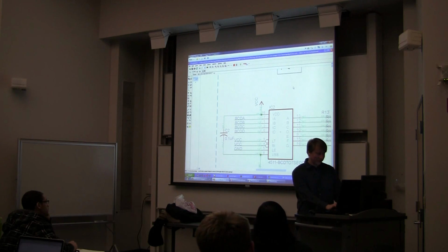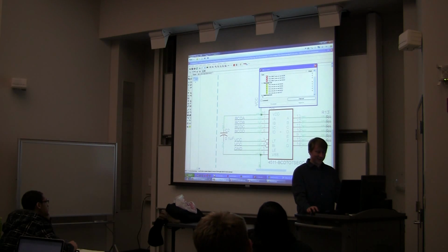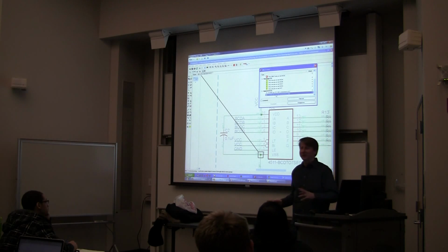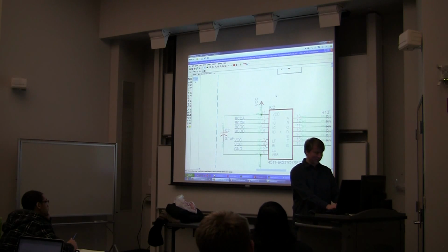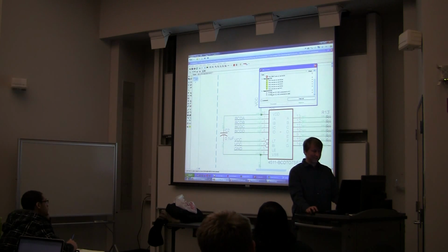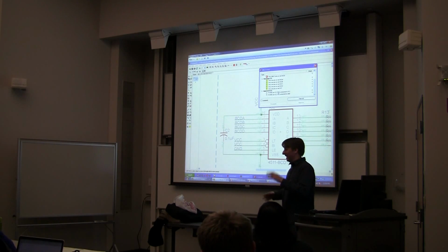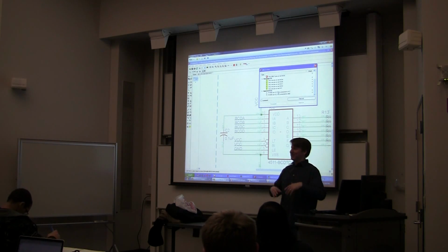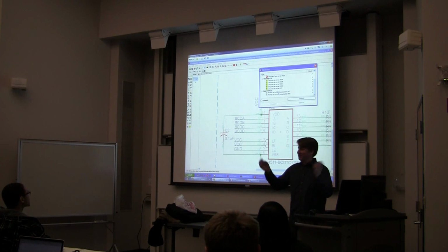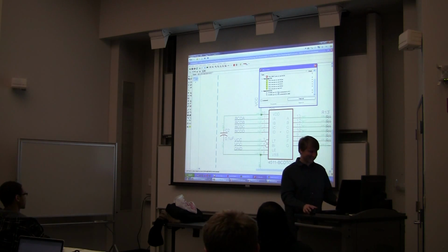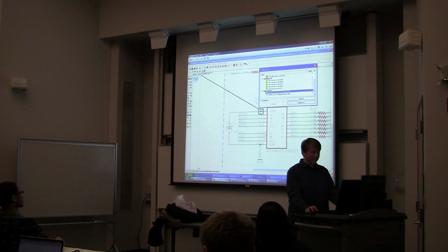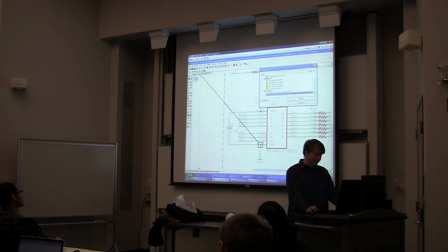Approved errors no longer come back when you type ERC. They're hiding here. Don't just approve all your errors, because you can also look specifically at your errors. So if you just have like 87 errors on your board and you just approve them all and submit it and hope that when you type ERC you get those errors, you say, oh, your board works great. No, you can check those. But those are the sort of ones that you can approve.